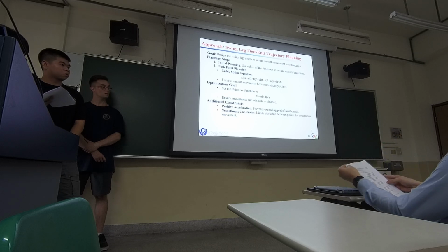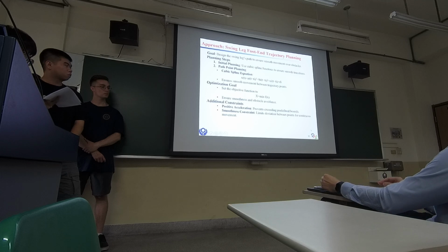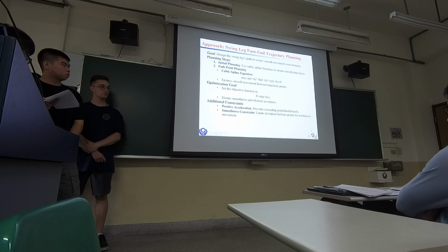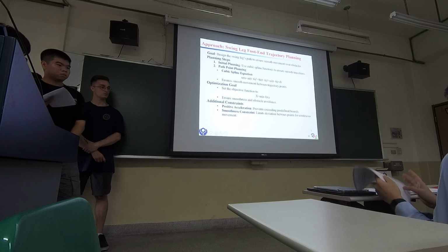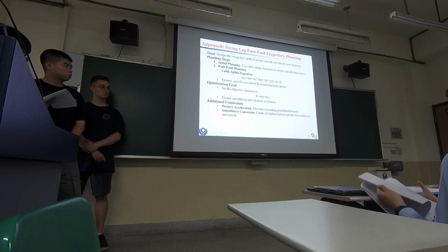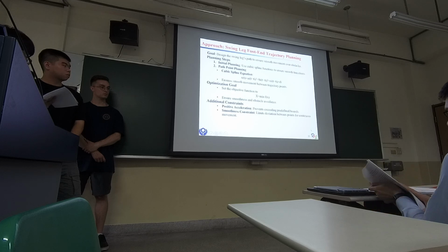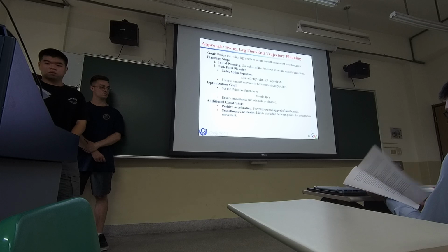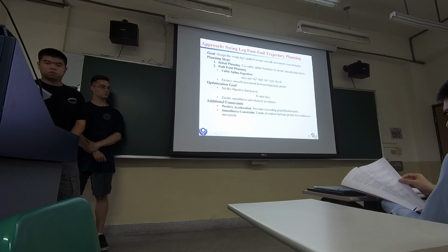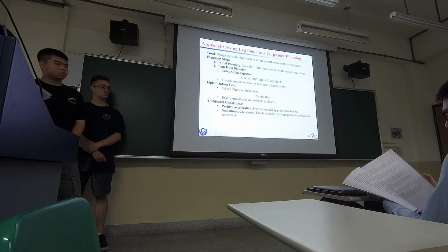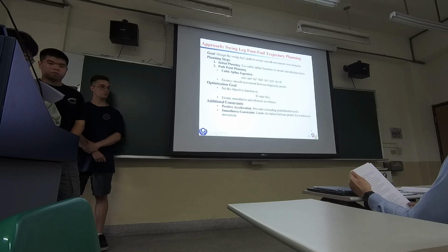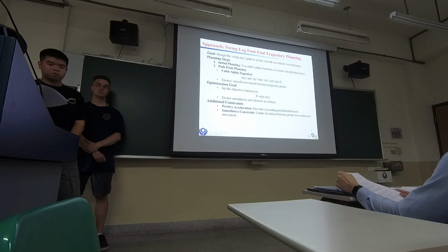Initial planning: we utilize the cubic Bezier function to ensure smooth transition between trajectory points. This helps to shape the path in a smooth and continuous manner. Path point planning: for each point along the trajectory, we calculate the path using the cubic Bezier equation. This equation ensures that the movement between points is smooth.